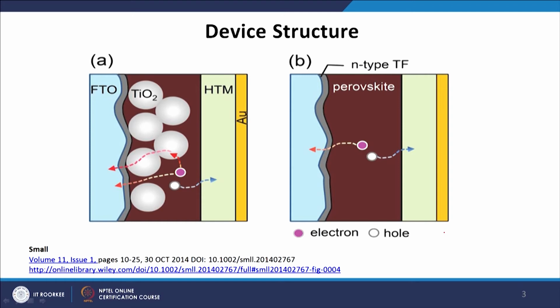But before that, what we need to know is what the different components are and what the role of those components is in a perovskite solar cell, right. So, let us take a look at a cross section of a perovskite solar cell. Now, as I said, there is this FTO, which is a fluorine doped tin oxide coated glass substrate, the conducting photoanode, and on top of that we put the TiO2 layer, the mesoporous titanium dioxide, and there is this perovskite layer here.